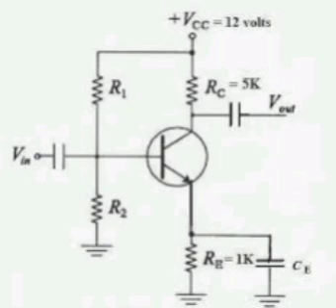Vout equal to 0.95 Vin. Vout by Vin equal to 0.95. Now Vout equal to Vin into RL by R plus RL. Vout by Vin equal to 100 by R plus 100. That equal to 0.95. R equal to 5.263 ohms.